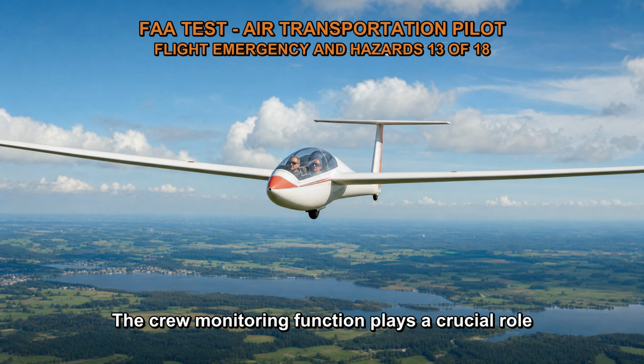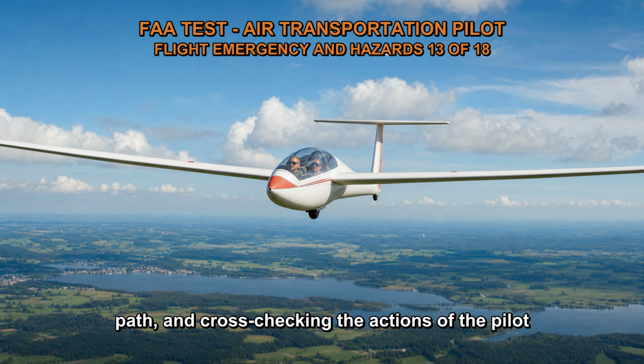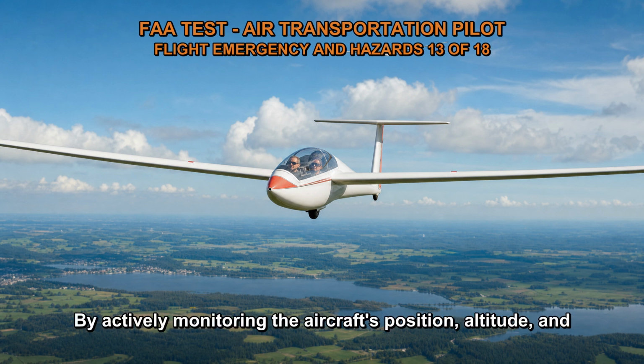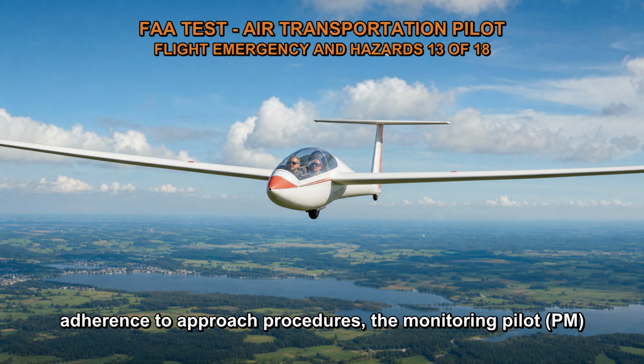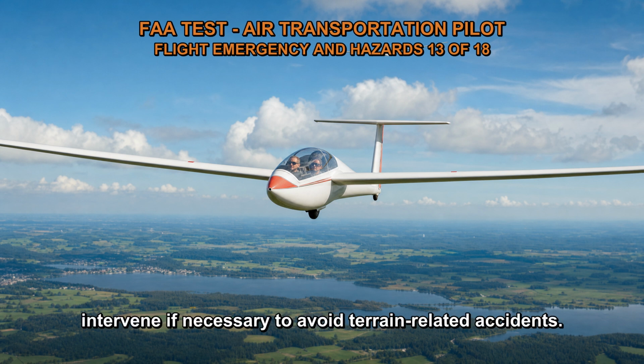The crew monitoring function plays a crucial role in maintaining situational awareness, monitoring the aircraft's flight path, and cross-checking the actions of the pilot flying, PF, to prevent CFIT accidents. By actively monitoring the aircraft's position, altitude, and adherence to approach procedures, the monitoring pilot, PM, can provide an additional layer of safety and intervene if necessary to avoid terrain-related accidents.